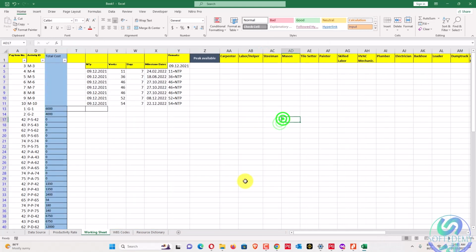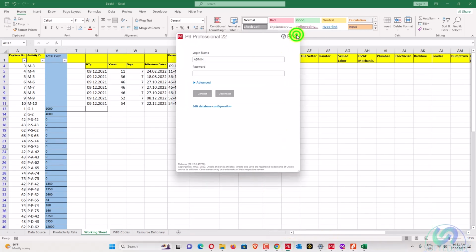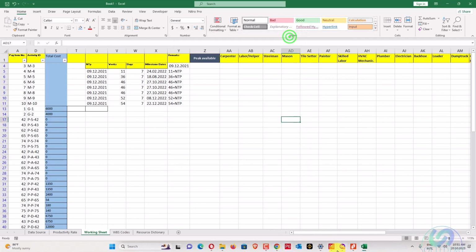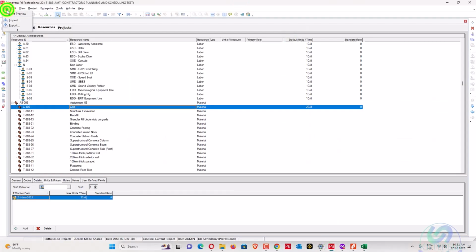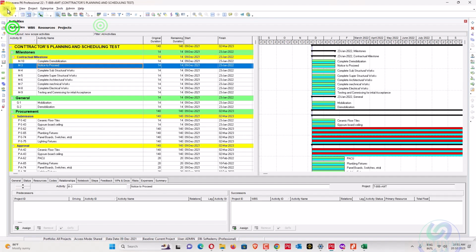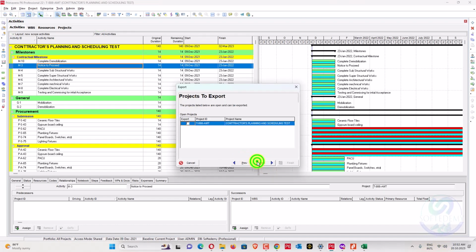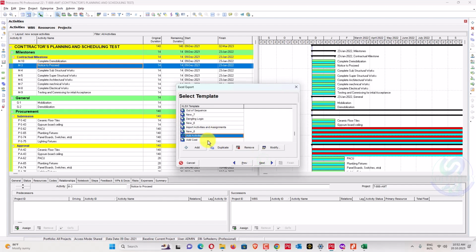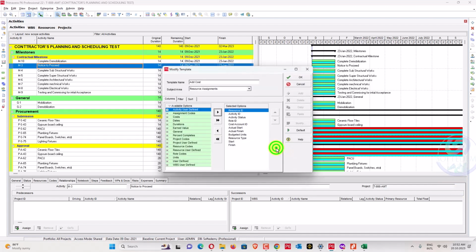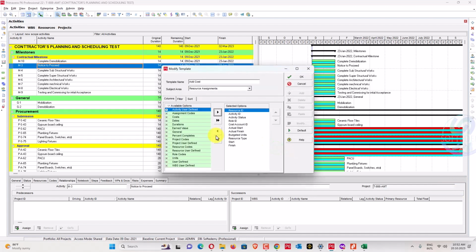Hide this one. First we'll go here, Primavera P6. Okay, why are we opening again? We have already Primavera P6 open. And now this time I will just go here, export my XLS file into resource assignment. In this step I will import all types of resource assignment, like my cost, my resources, material, non-labor, labor, everything I will import.